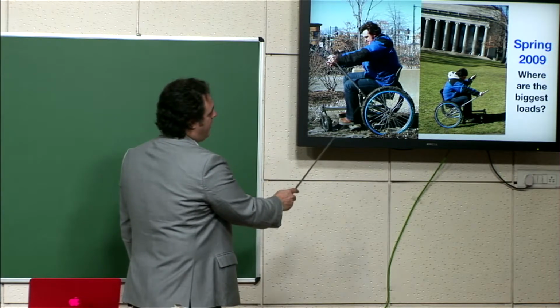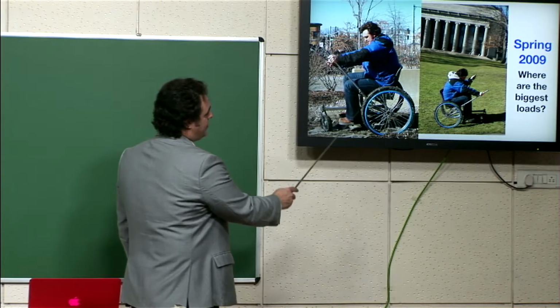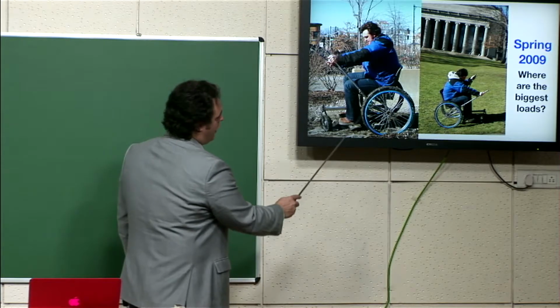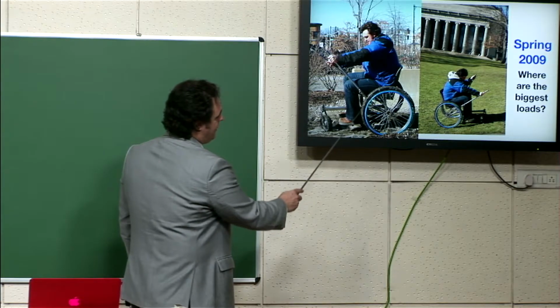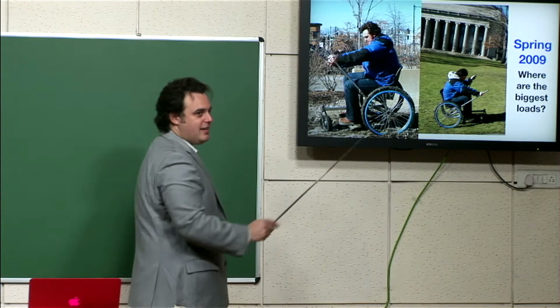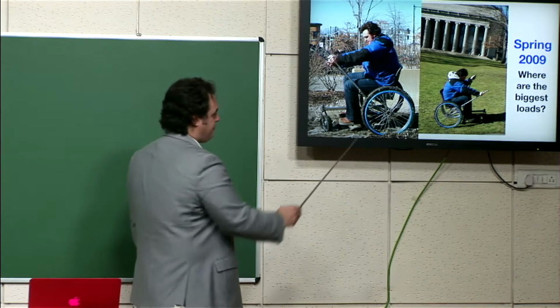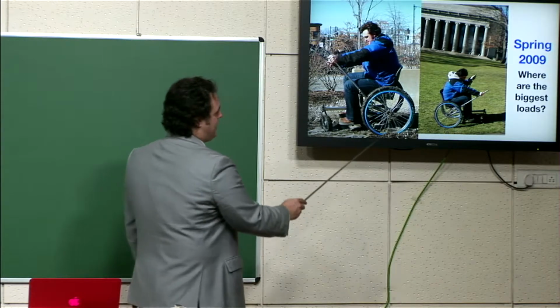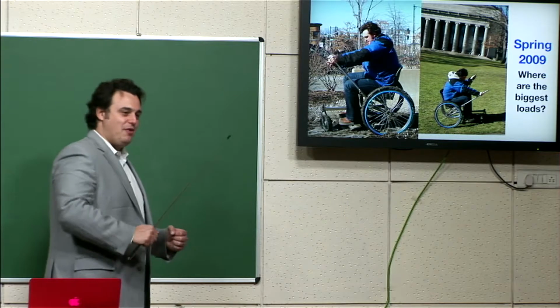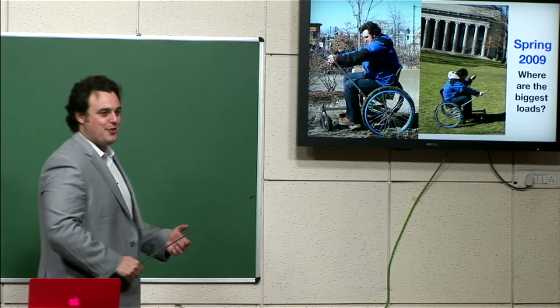Let's say it's 100 pounds and this lever was longer. This is about a 4-to-1 difference. Or actually, sorry, look at this radius here to this lever length. We're talking closer to 10-to-1. It's around 1,000 pounds, right? What we realized is that this chain tension would actually warp the frame. It would flex the frame and the chain would fall off the drivetrain.